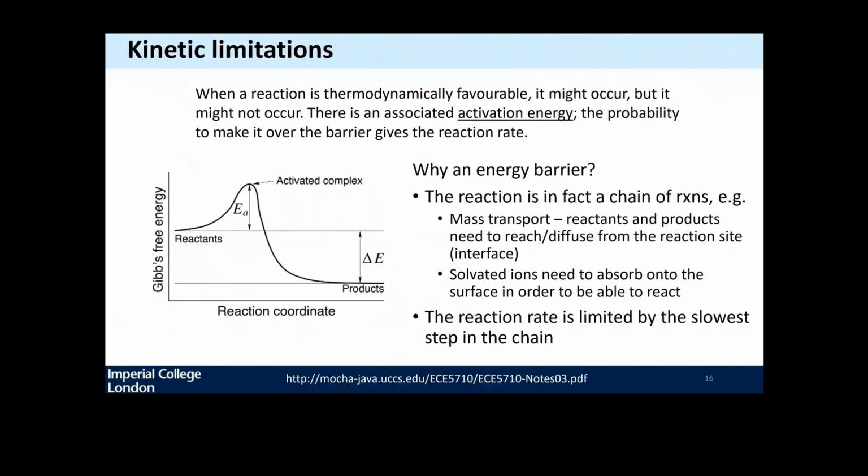The next step to add is that as soon as I charge or discharge, so I use my battery, I'm outside thermodynamic equilibrium. I'm sending a non-zero current at that interface between the electrolyte and the electrode. And this comes with an activation barrier to drive a reaction outside of equilibrium. And I think you probably have seen this as well in other electrochemical systems.